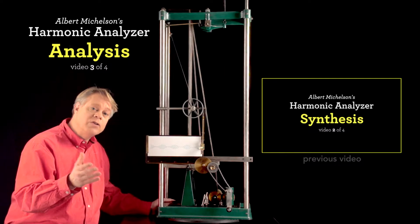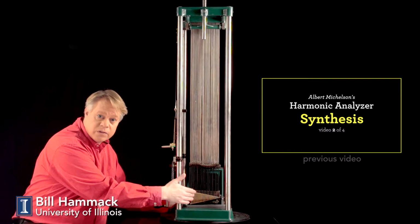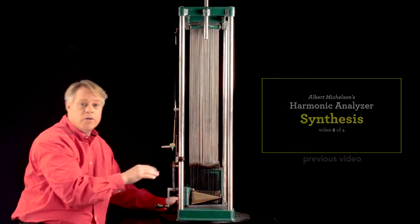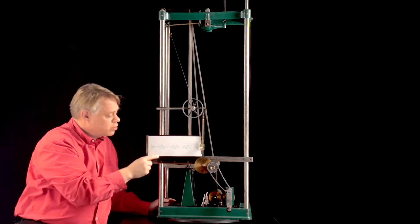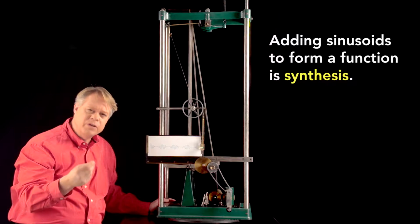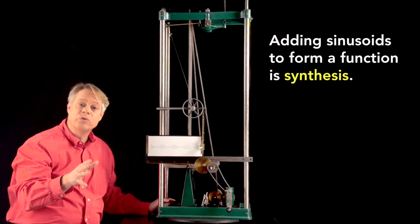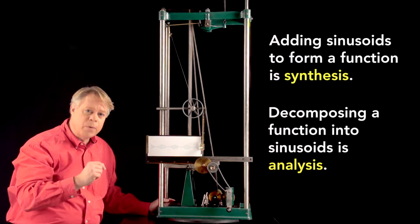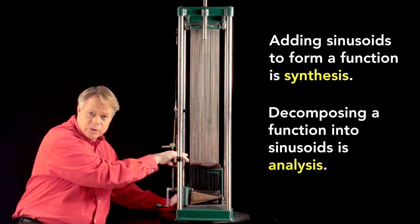In the previous video, I showed how turning the crank on this machine generates 20 different frequencies, also known as harmonics, which are turned into cosines here, multiplied by coefficients, then summed, magnified, and the resulting function plotted here on the front. This process is called synthesis. But this machine is called a harmonic analyzer, which means it can be used to solve the much more difficult inverse problem called analysis. For example, if I want to plot a particular function here, how do I set the amplitude bars to produce it?